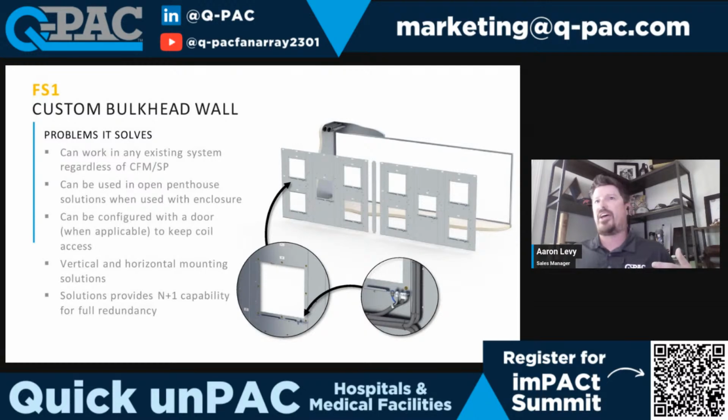So we can have a fully redundant system or near fully redundant system, depending on how we specify it. A lot of times we work from a building's schedule print, and depending on how that schedule is written, it could be oversized for the unit, which allows us to either have inherent redundancy built in, or even remove fans from a system to make it more efficient, with spare fans already on site built into how we've integrated the system. That's inherent in how this wall design is.